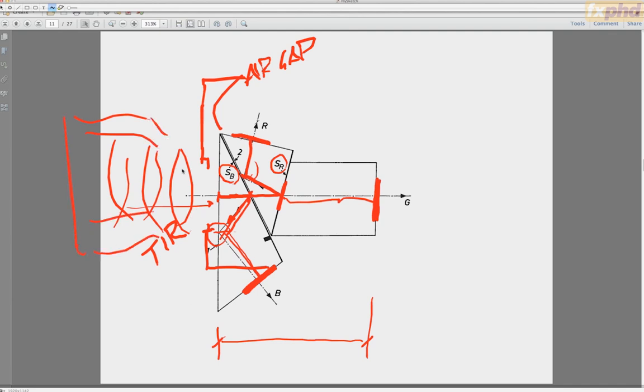But from the back of the lens, from the flange to the sensor, this distance, which is called the flange focal distance, and this is all about the back focus of a camera, it's incredibly long for a 3CCD camera.